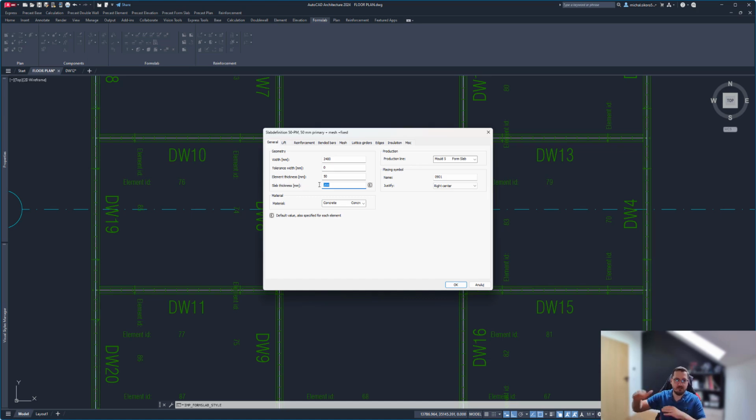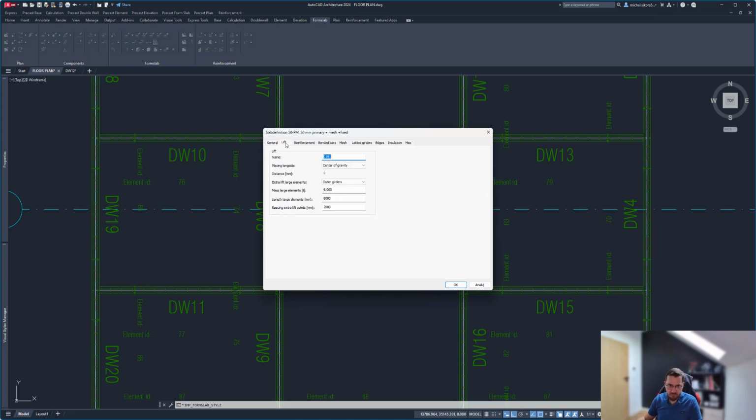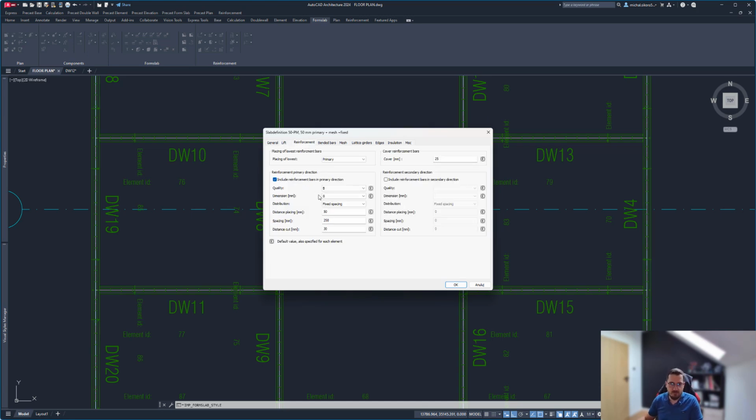So basically not how much concrete you pour over the form slab, but rather how thick the form slab is with the concrete poured over it. Anyway, lifts are automatically placed in those form slabs as well, depending of course on the mass of elements. The reinforcement specification, if we want the reinforcement just in one direction, so basically longitudinally.